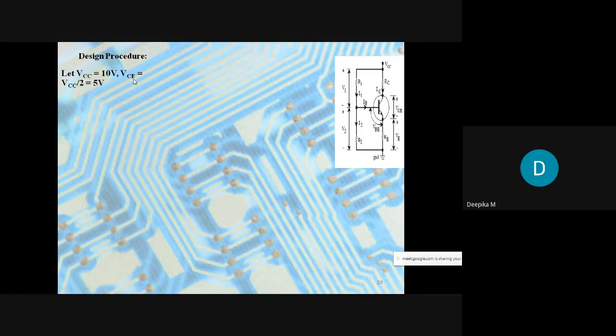Usually the voltage between collector and emitter will be half of that, so therefore it will be 5 volts. And therefore IC is 4 milliamps, beta is 100, and IB is nothing but IC by beta, which is 0.04 milliamps. This can be calculated by selecting these ranges.